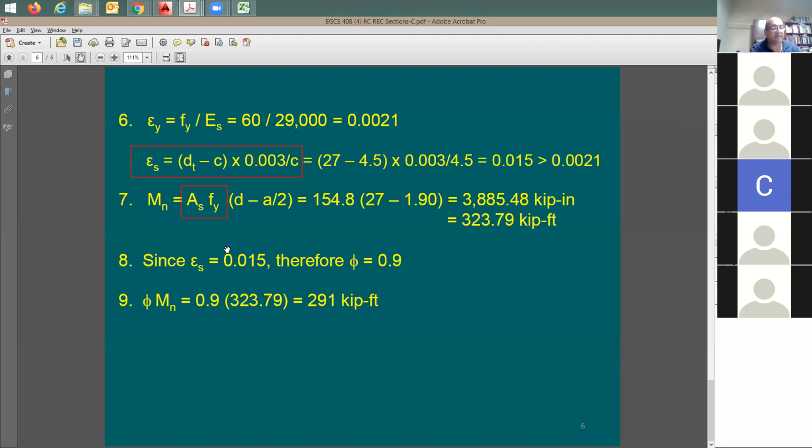Right? Because these are the numbers that you have seen. Now, once you start to practice, you need to come up with this value. Usually, you're going to have a senior project engineer that you're working with in this project. He's going to tell you exactly which value to use. Just so you know, if you use 2,500 psi, which is the lowest number in the ACI, you don't really need to have official inspection.